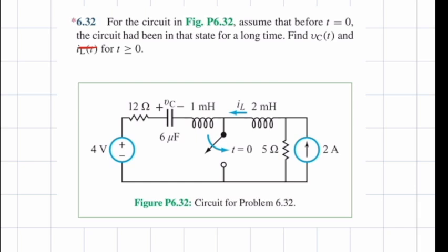So for this, you remember the transfer function method? After the switch is closed, or after t is zero, you put it in its final state and then solve it. Put it in the final state and then find the transfer function. And then you can find the characteristic equation on the bottom, to determine if it's underdamped, overdamped, or critically damped, and then you know the formula of the final solution. And then you come up with a table of ones to find those values.